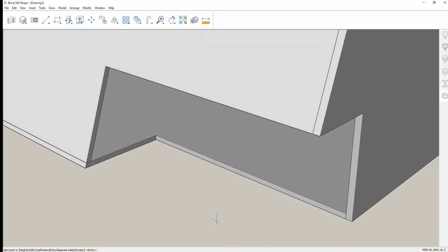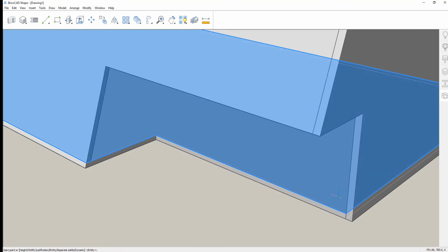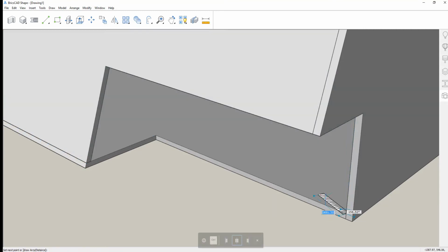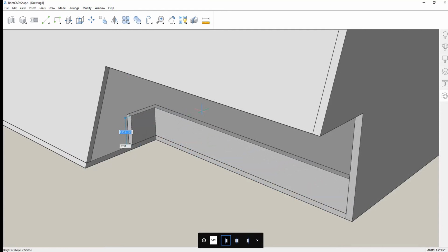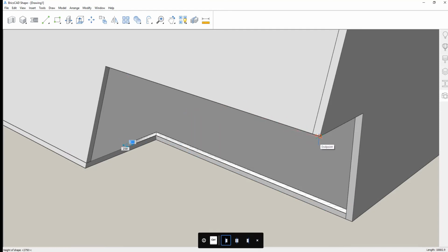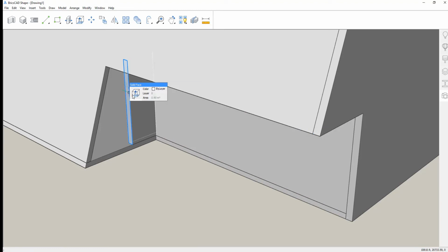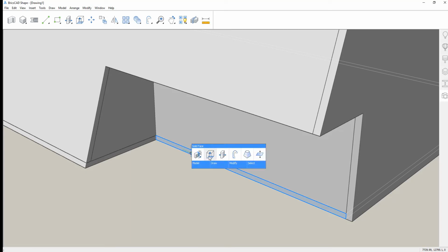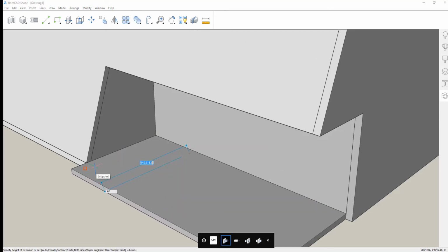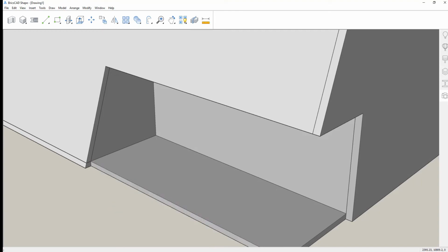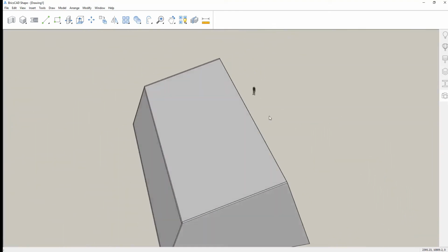We'll use the poly solid command. Why? Well, because it has multiple uses. In this case, we'll use it to simply drag out a wall profile, snap to existing geometry to get the height, and then run that face up against the next face. Select the front edge of the slab as a new boundary and drag it out to create the floor slab for the entryway.